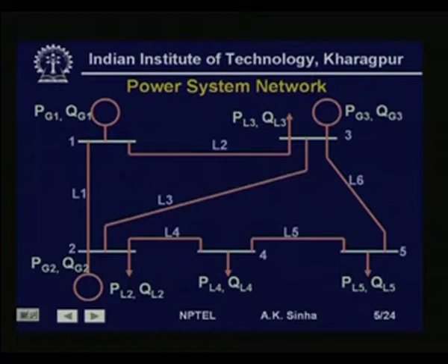We have also seen in this diagram that some of the generating bus bars, like bus bar 2 and bus bar 3, also have loads connected to them. In fact, most generating bus bars will also have some load connected, because if you are running a thermal power station, then the auxiliaries as well as the substation supplying local power for the residences in that power station all have to be supplied, and these are the loads connected to that bus bar.